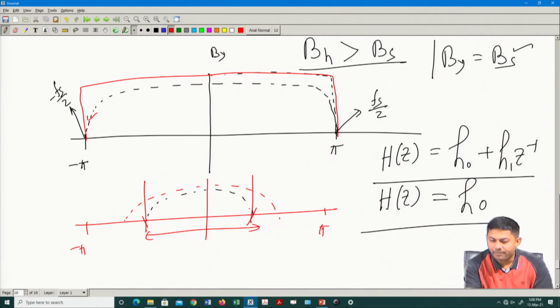So, if within my pi to minus pi my data just fits, and I am saying that after transmission my data has no distortion, it simply means that within my window of view, if it is exactly tight, my complete 10 megahertz, that is my transmission bandwidth, it is as if my channel is an all pass filter. It is an all pass filter, right?